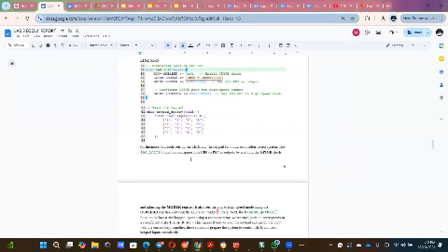All right. So for line 51 to 69, as you can see in the picture, this code sets up the LEDs and the keypad for a microcontroller-based system. The LEDs_initial function configures pins PB0 to PB7 as outputs by enabling the GPIOB clock and adjusting the mode register.